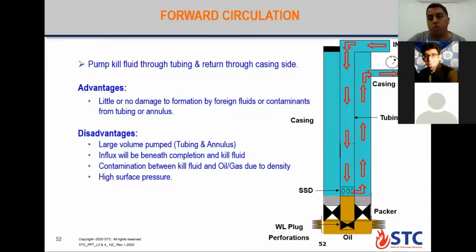If you need to use it, in this case it can be, but most company policy is not to rely on the downhole safety valve. But if you have a problem at the surface Christmas tree and the string is filled with oil, for sure you will shut in with the downhole safety valve in case you don't have any tool inside the well. Okay, got it.